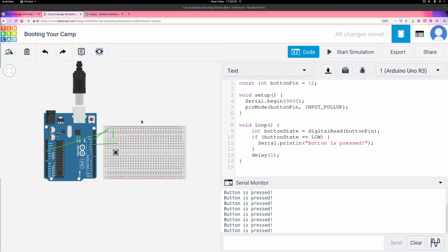Before, we had a blinking LED that would turn on and off, which was very nice to have. Oh yeah, I probably should have saved that circuit, shouldn't I have? Whoops. But now, what would be nice to do is create an LED that fades smoothly on and then smoothly back off. So a bit like a pulsing as opposed to a blinking light. And this shows off the PWM, or the fake kind of analog output.